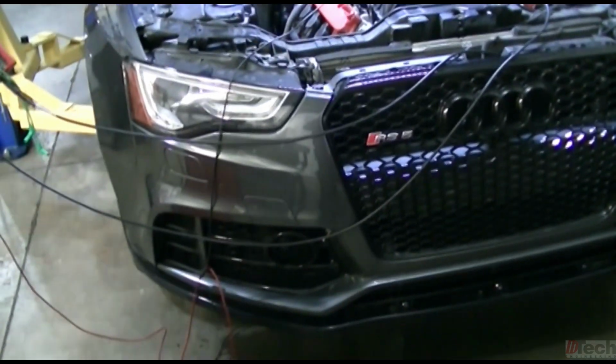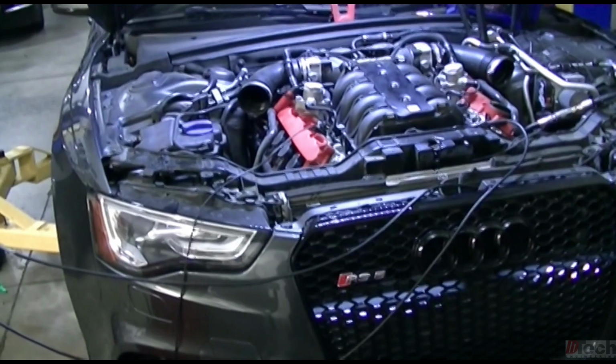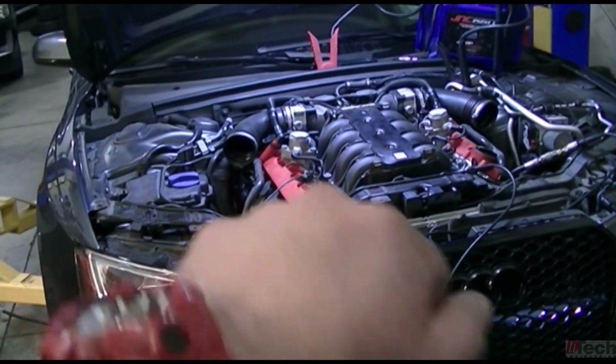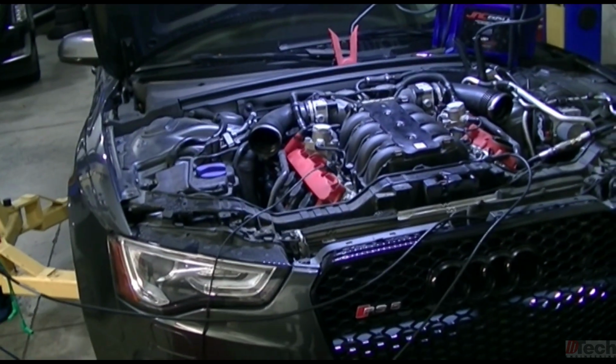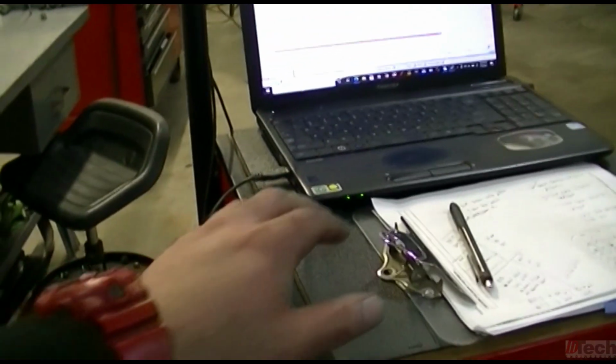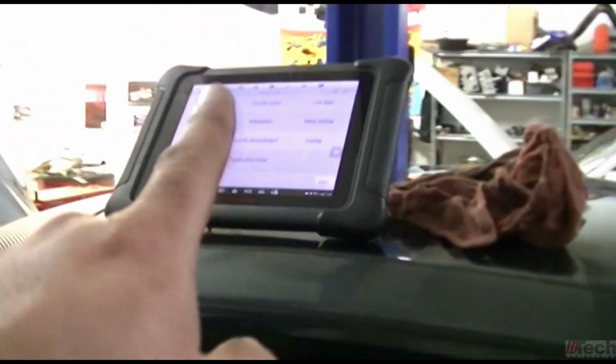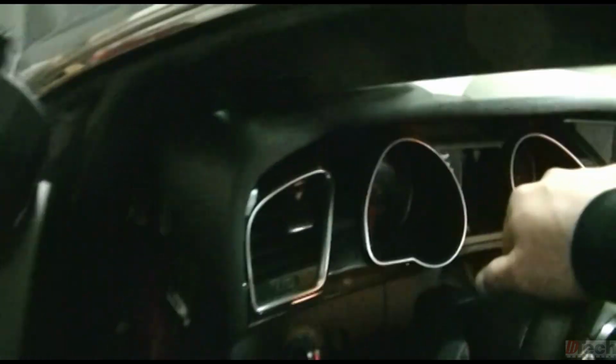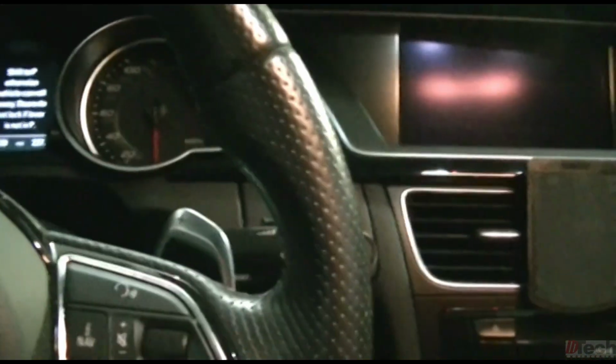Alright, so for now, the next procedure that I want to do is measure bank to bank in cylinder, running with all 4 oil control valves plugged in. Now we are running here and should be ready to crank it. Also, I went in and cleared all the faults that I had set up to this point, because I wanted to try to activate or run the variable timing as it would normally try to. So I wanted the computer fault free.